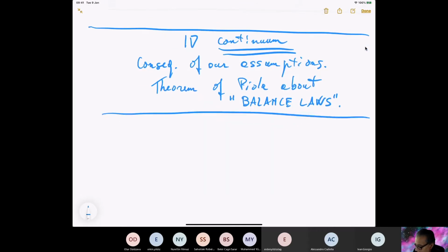So our hypotheses are: W depends only on F. Actually, W of F is equal to W bar of C of F, because the deformation energy depends only on C. You remember, C, we discussed a lot, is F transpose F, and it is 1 when you have a rigid placement, and when it is not 1, then you have a deformation.